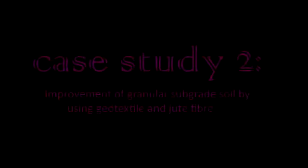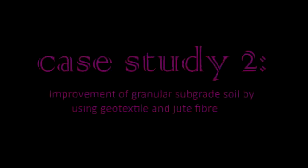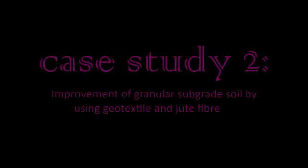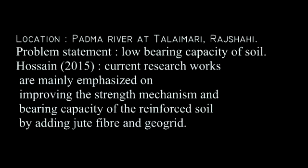Next is our case study 2, about the improvement of granular subgrade soil by using geotextile and jute fiber. It is located in the Padma River at Talaimari, Rajshahi, India. The soil at the Padma River has a very low bearing capacity. Thus, the current research works mainly emphasize improving the strength mechanism and bearing capacity of the reinforced soil by adding jute fiber and geogrid.